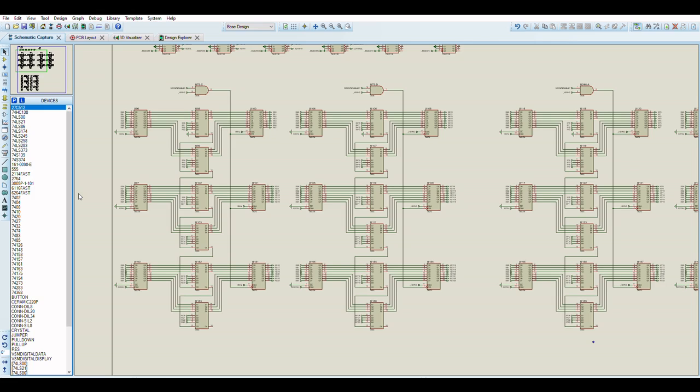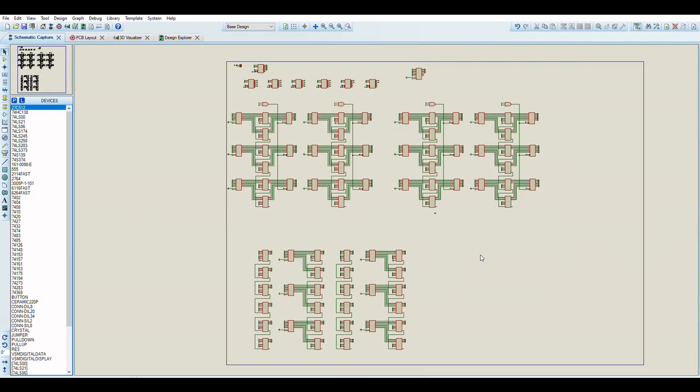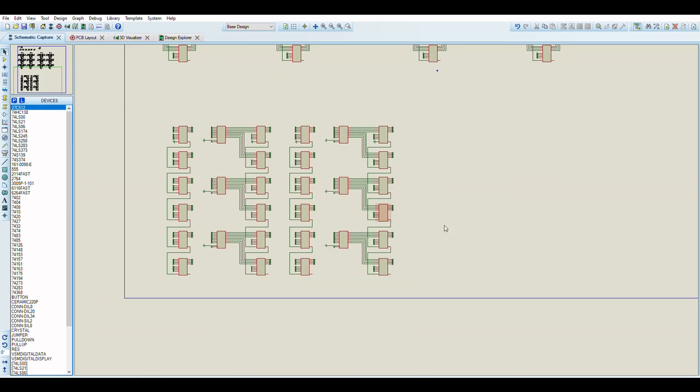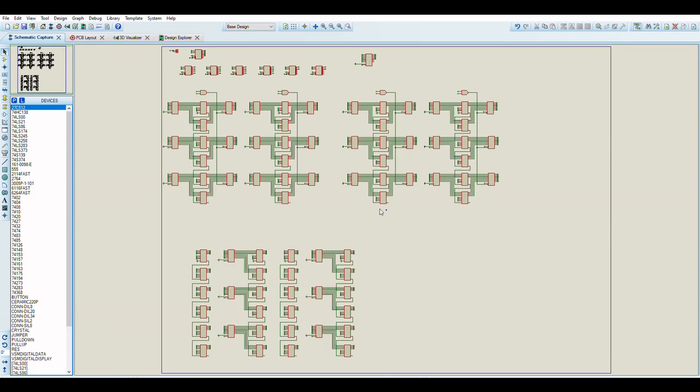So all of this logic here deals with accumulating these different values and latching these different values depending on your horizontal and vertical pixel position in the screen on a sequential per pixel basis or a per scanline basis. All of these accumulated values eventually come out into the various different registers for X and Y position. And these X and Y positions are then used in the next sheet.